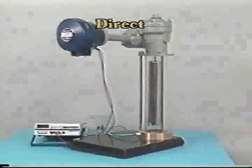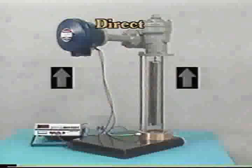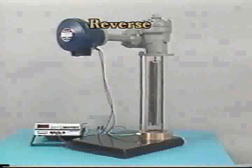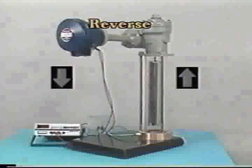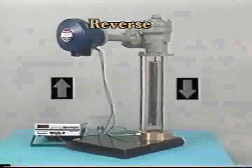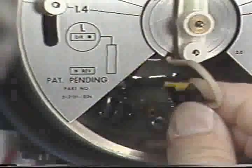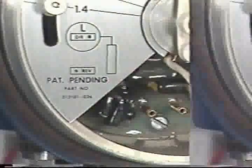Displacement level transmitters are classified as direct or reverse acting. With direct action, an increase in level also increases the output signal, and a decrease in level decreases the output signal. With reverse action, however, an increase in level decreases the output signal, and a decrease in level will increase the output signal. Before calibrating the instrument, set the plug to control the action. Here, the plug is set for reverse action. If this installation were direct acting, you change the position of the plug this way.